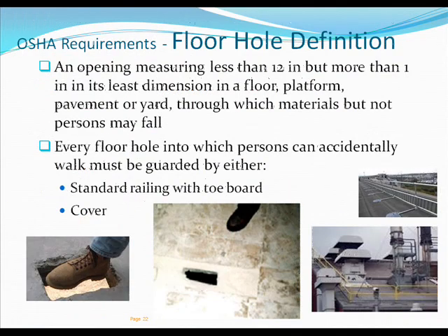Floor hole definition. An opening measuring less than 12 inches but more than 1 inch in its least dimension in a floor, platform, pavement, or yard through which materials but not persons may fall. Every floor hole into which a person can accidentally walk must be guarded by either standard railing with toe board